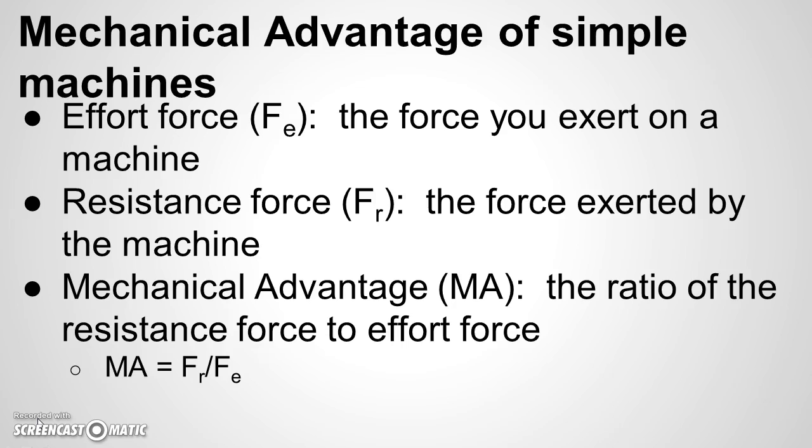If it is near the fulcrum point, it will travel a relatively short arc, a short distance. But your end of the lever can travel a great distance. And because you're moving it a greater distance, each portion of that motion is easier to perform. This is the mechanical advantage of something such as a fulcrum in the example given. It is the ratio of the resistance force to the effort force. This type of thing typically must be measured.